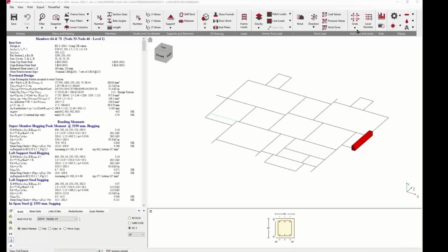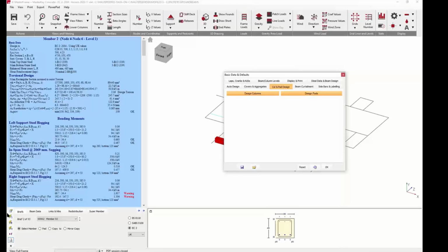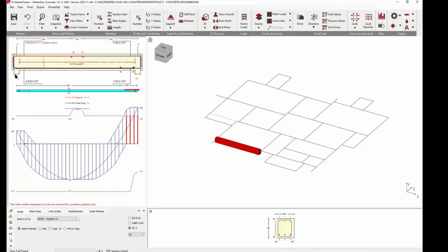Well, the beams are 350 wide, but what you're looking at, oh, sorry, wrong button, is this little support here. By default, it assumes 200 wide for your curtailment and everything, and you can put in the width you want for this, and it helps your shear design. The other thing I would say here is that everything is good.